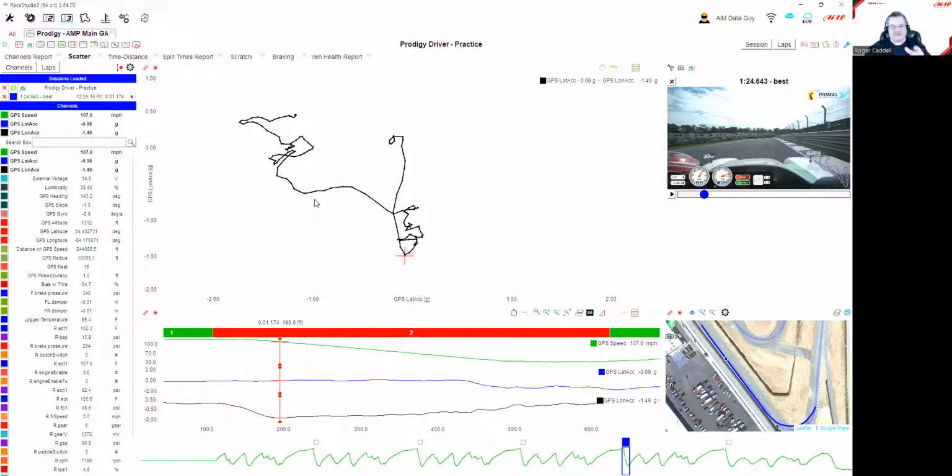That's mathematical, right? Does the track have fall off? All of these things fit into it, right? Is the car loose on entry? You as a driver have to do things in order. If a car is loose on entry, you may have to back off of the lateral before you turn in. That's part of your job as a driver, to drive around whatever the problem is.